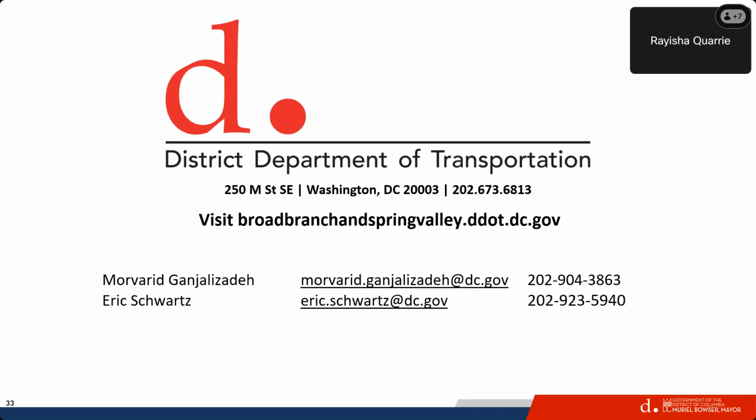So we need to have more green spaces. We can't just have tanks, reservoirs, and concrete to manage stormwater. I believe the tunnel project you're mentioning is also a DC Water project. These are mostly focusing on detention. Detention means storage. They just capture the water so it's not on the streets, but they don't treat the water, which in the combined sewer system in DC, which is the center of DC, is more practical because we don't need to treat the water. But in the border, you can't just have reservoirs all over the city. You need to treat them. So the tunnel or pipe doesn't have the treatment, if that makes any sense.